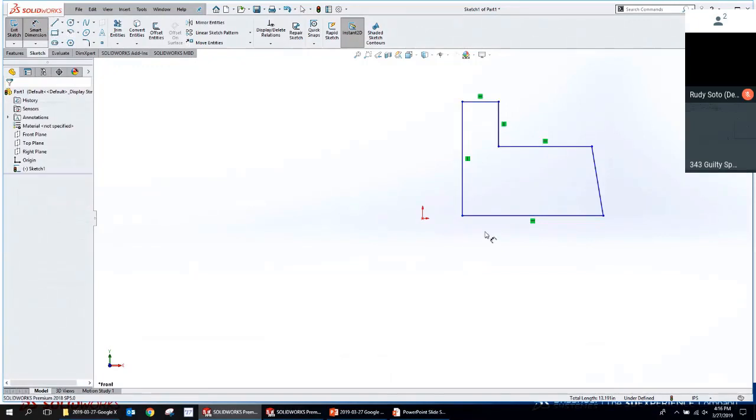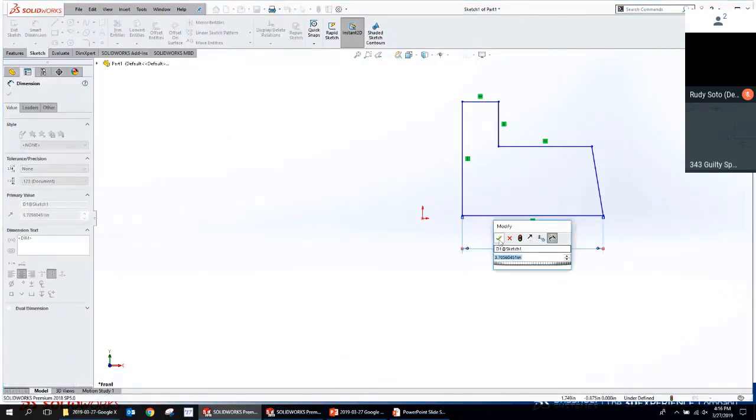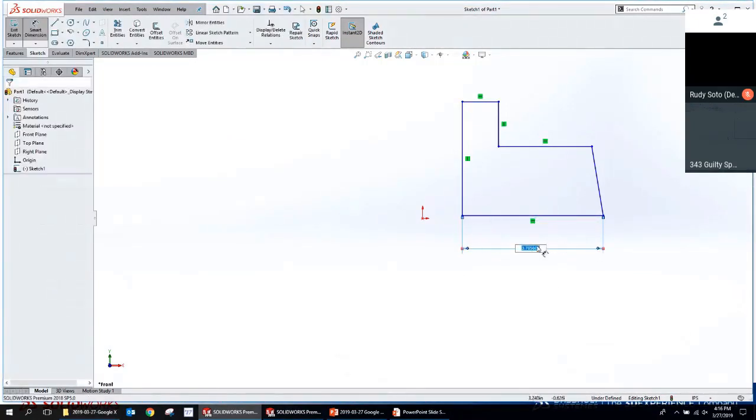So what Instant 2D does is this is where our dimensions changed from being a modify spin box to being this. This is something that comes up for a lot of users who are migrating into the newer versions of the software. You guys familiar with this? Okay, so with Instant 2D on, it's a little bit maybe awkward to change the dimensions, or especially to delete